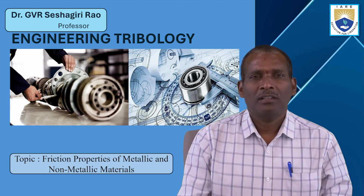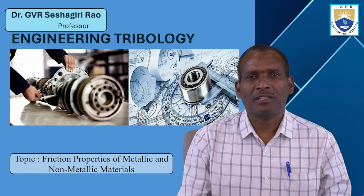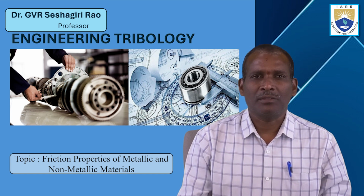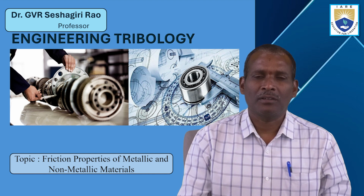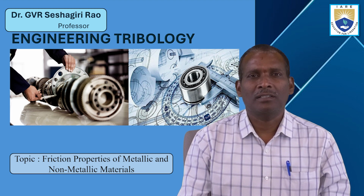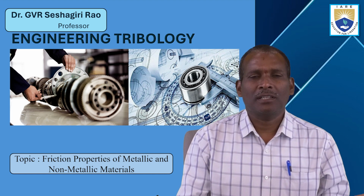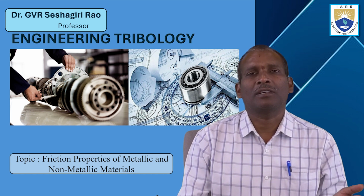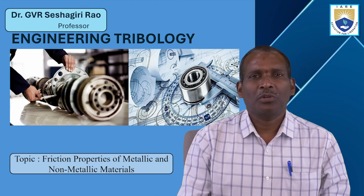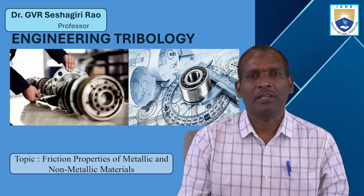Whenever two components, two machine elements, are in relative motion, there is friction, and due to the friction wear will be present, and then lubrication is also important. Whenever friction and wear occur, you have to implement a lubrication system so that you can reduce the friction. If friction is reduced, then you can reduce the wear also. So you should concentrate on friction, wear and then lubrication.